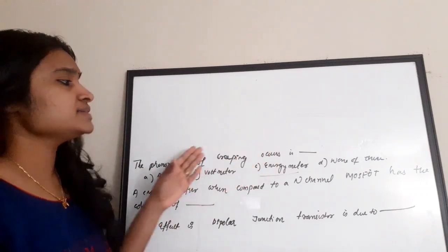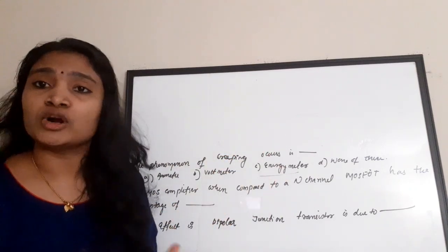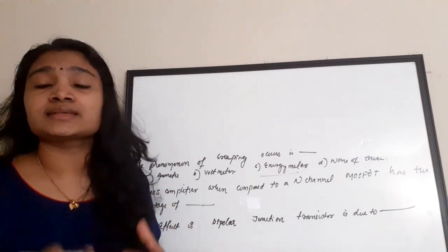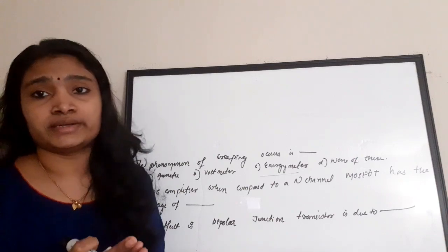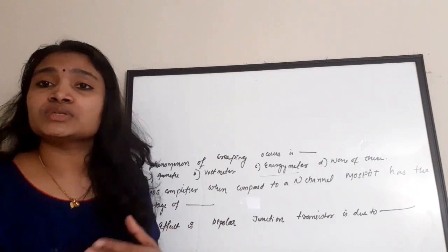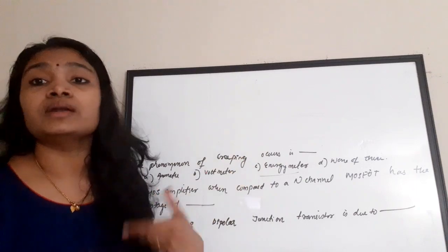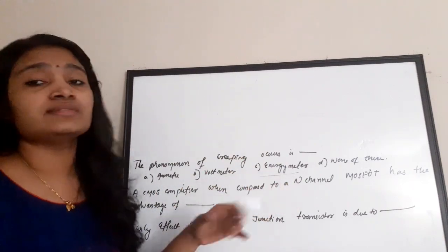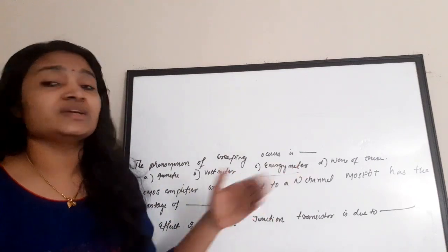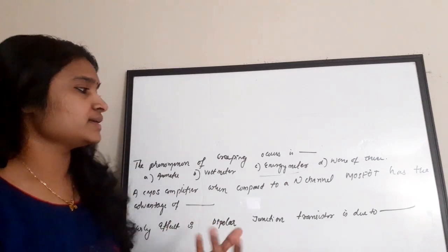Okay. So this creeping is a phenomenon in which, for finding the energy or for wattmeters, there are coils, aluminum coils or aluminum disc. This disc rotates even when no load is connected. So we connect a load to measure the energy or power. Even when no load is connected, due to some errors, this coil or disc rotates and this rotation is called creeping. Okay, so this happens generally in the meters where we measure power or energy. Correct answer is energy meter or wattmeter. If it is given in the option, the correct answer is that.